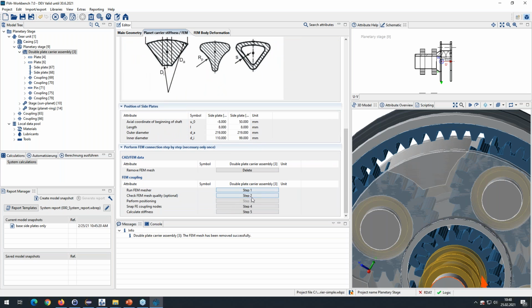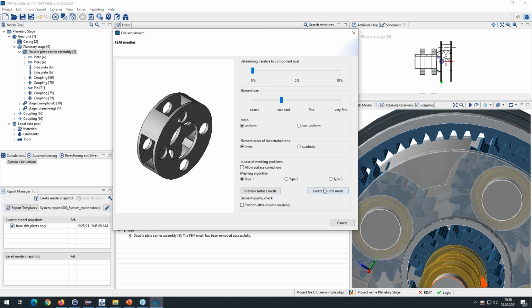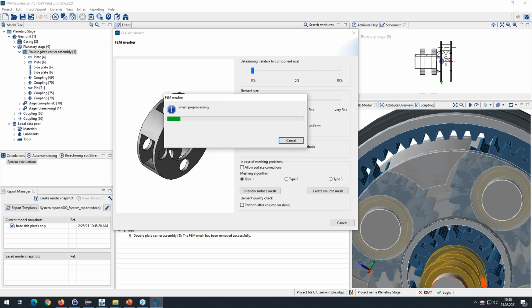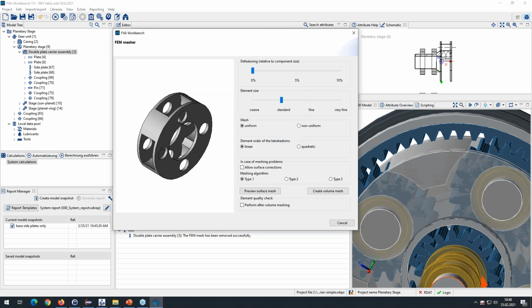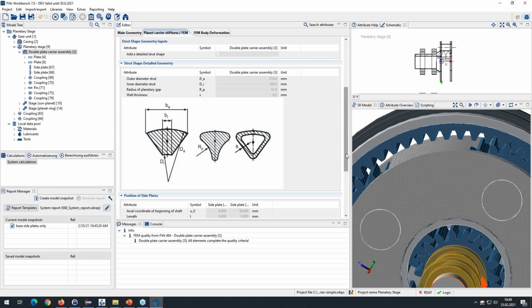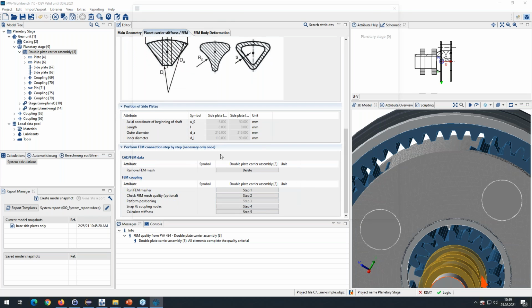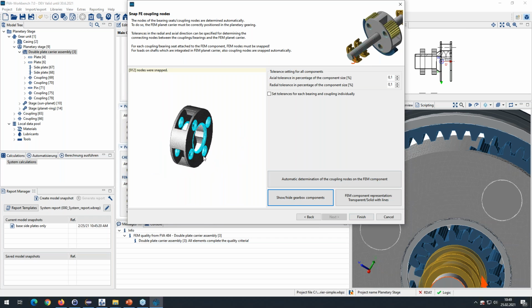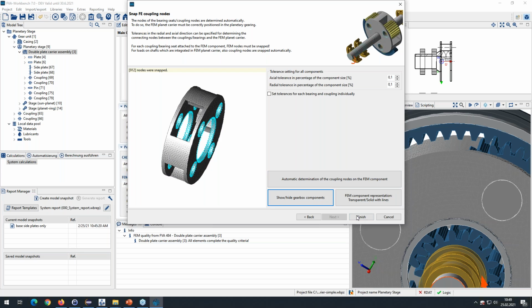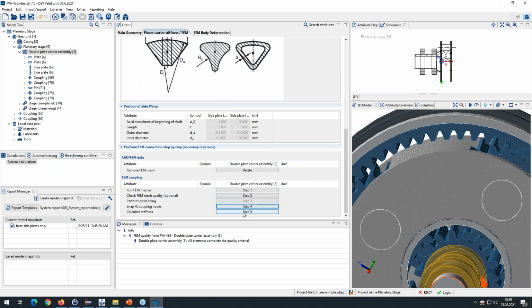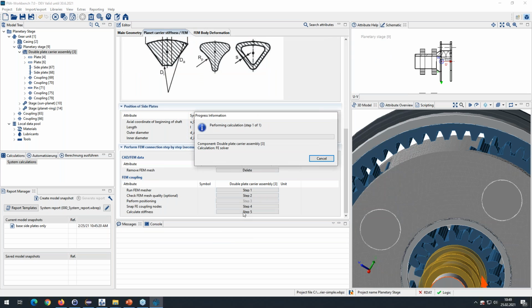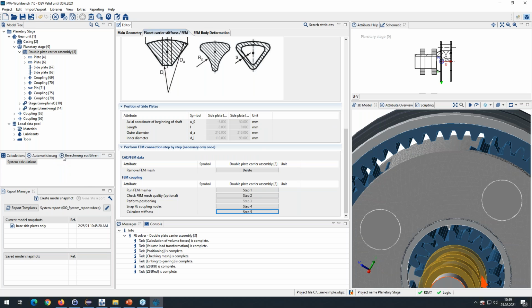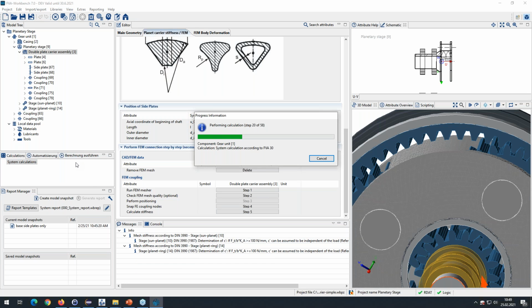Then let's now snap. Oh, sorry, I forgot to run the measure. You see we have checks everywhere. So we bring you to the solution that you would like to have. So we have now the mesh, we snap the nodes, and here now same nodes are snapped because only the struts are included, so no changes here. We can compute the reduced stiffness matrix and can directly run our system deflection.